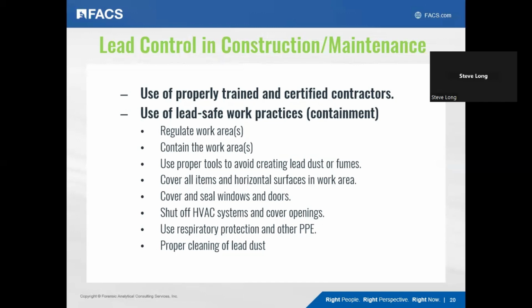And then we look at the use of lead-safe work practices. So if we need to disturb lead-based paint, maybe for repainting, it may be demolition of some walls and things of that nature, then we want to be sure to implement lead-safe work practices, or in short, containment. So these would be practices that prevent exposure and capture dust, prevent us from leaving dust behind after construction work.